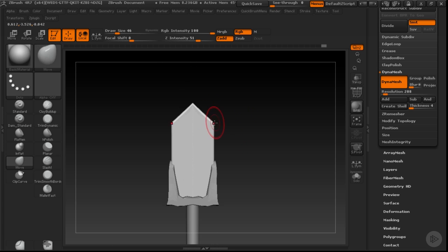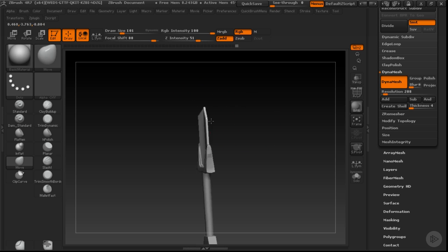What this means is also now that I can start to adjust the shape of this a little bit more. If I wanted to get a little bit more of a taper in some of these pieces, I can't quite get that taper because my movement's just a little bit too soft. Make sure that you change your focal shift. So if I change my focal shift to a small point in the center, then when I do this operation, I can get a much smaller point coming out of that. It's really handy, gives you just a bit of an ability to taper things just a little bit more than you were doing before. So that's pretty decent.